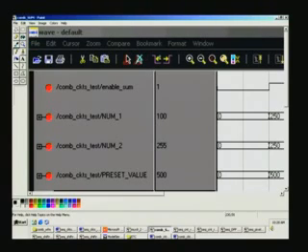And we have also seen how to use transitions of waveforms, whatever you had marked or highlighted, by merely pressing here, and along with shift, if you press here, all this will be highlighted. So whichever signal you want to highlight, you can use that one. In addition, for an additional signal you want to highlight, you can use control and press at the desired point.